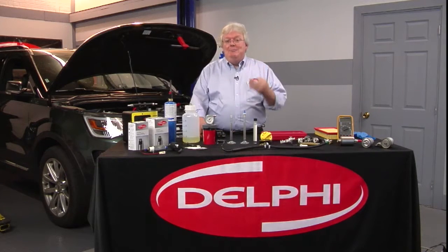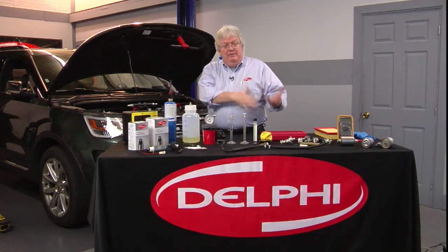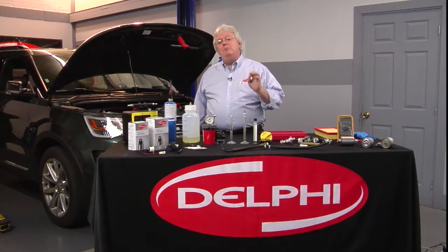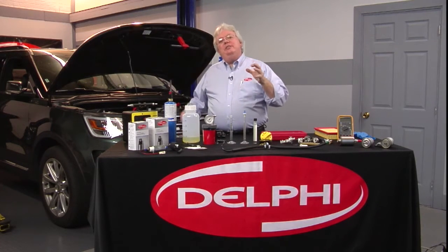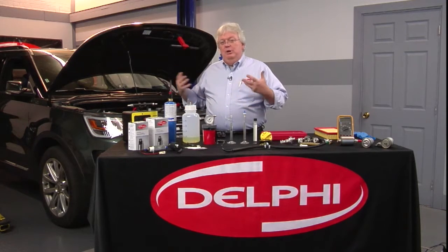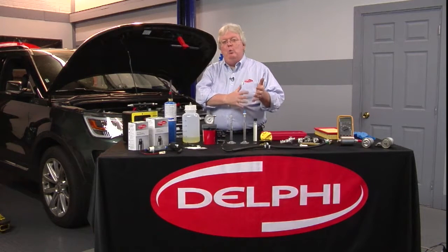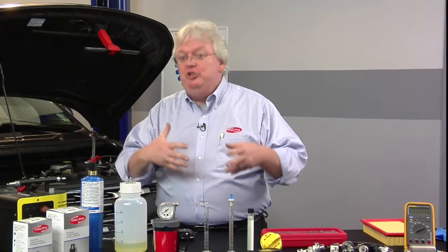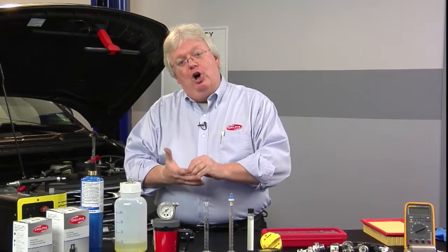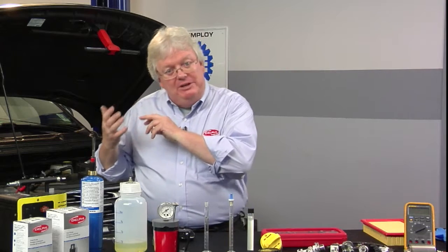But if somebody gets some E85, maybe half a tank, and they have the other half of the tank that was already in the vehicle that's E10, then you have drivability issues, very severe, and fuel trim numbers will go positive because the alcohol content in the tank doesn't have enough energy, and the computer doesn't know you have alcohol, so it doesn't adjust the base pulse width like a flex fuel vehicle would with a virtual sensor, which is using fuel trim after a refuel, or an actual alcohol sensor, a sensor that measures the alcohol content going from the tank up to the engine.